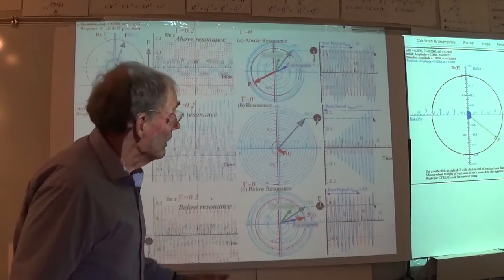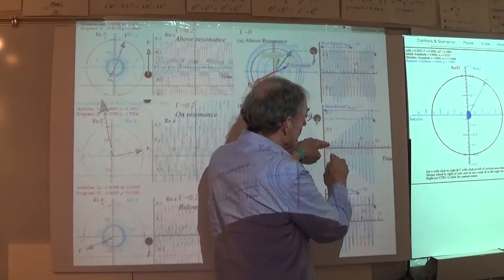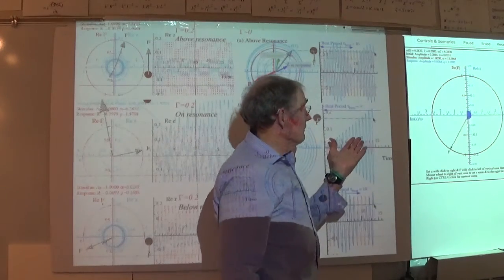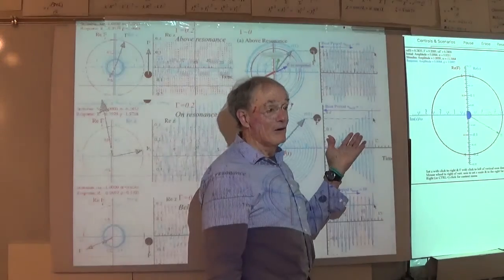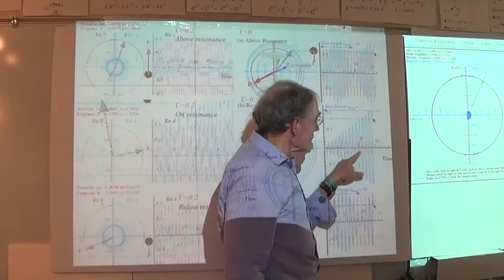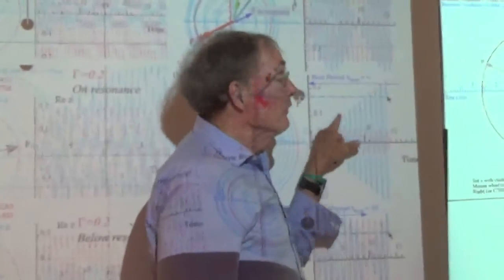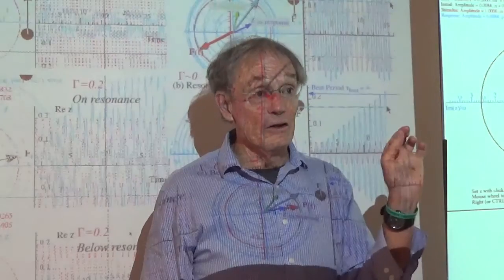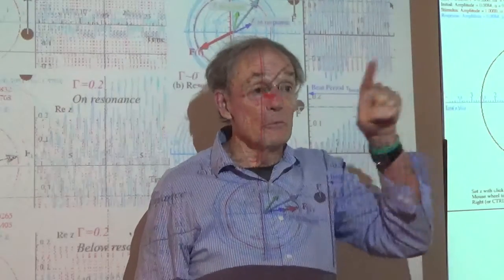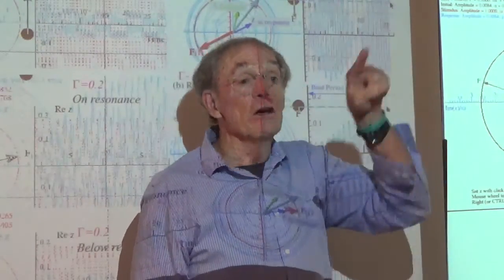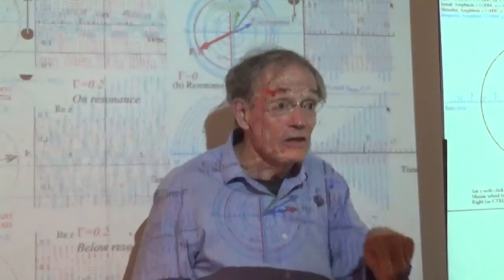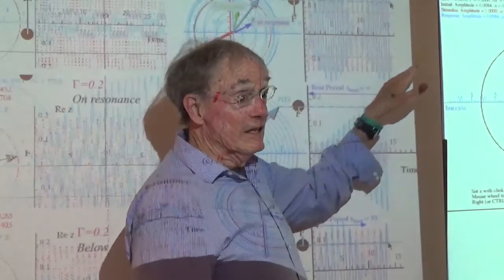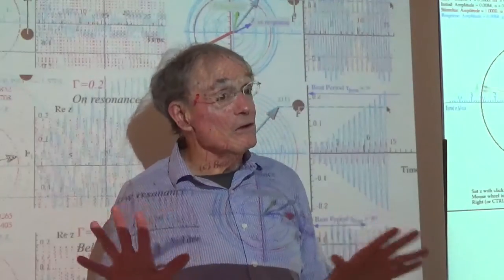But in any case, here I'm talking about resonance, and what I'm talking about is a straight line. This thing just builds an Archimedean spiral, a linear increase each time, getting the DC response quantity added to the radius of the circle that you're building bigger and bigger. Each time you get another DC, another DC, and you get a linear growth in the amplitude. That's the best a linear oscillator can do, you see.